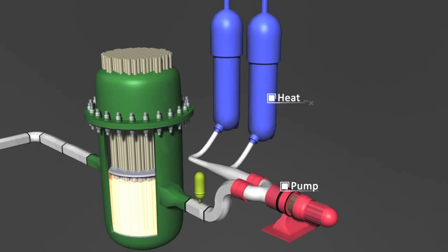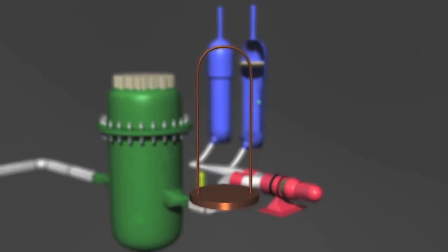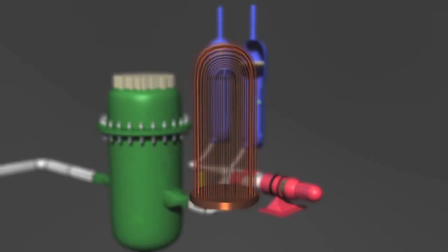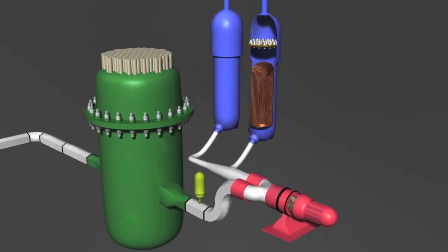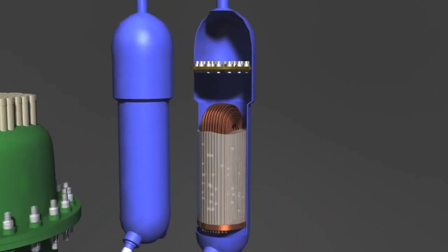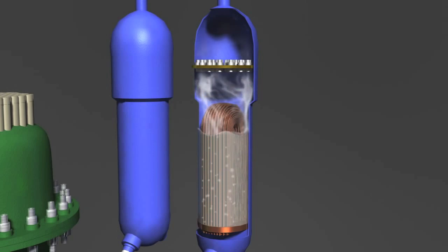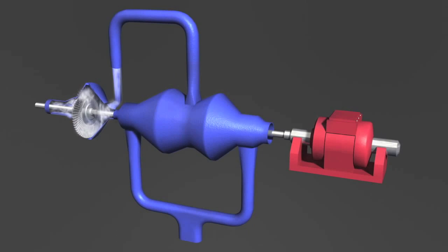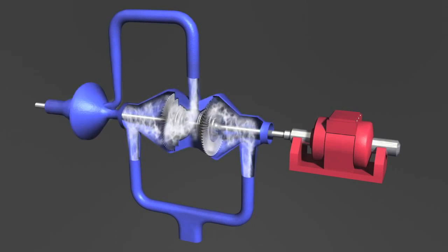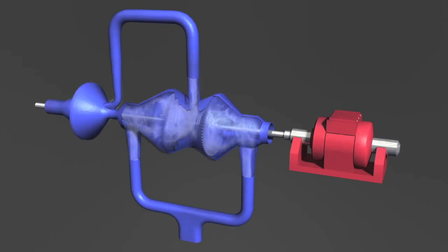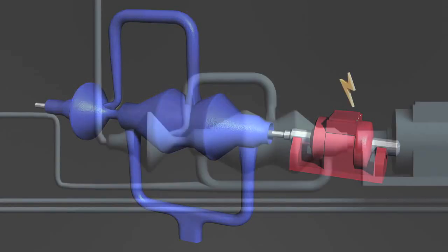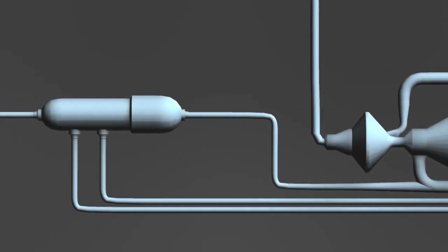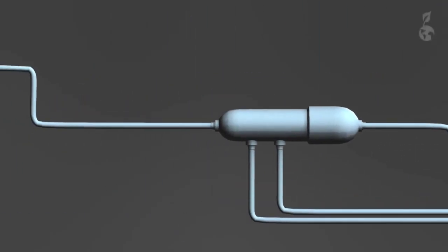The heated water is pumped to a heat exchanger which generates steam, since any water that comes in contact with the heat exchanger will absorb the thermal energy. The steam that is produced is then directed to the turbines. The first one is generally high pressure and the next two are low pressure turbines. All of the turbines are connected by a shaft to the electricity generator, which produces electricity from the shaft's rotational energy. The steam is then converted to liquid form by a condenser and returned to the steam generator.